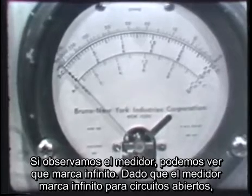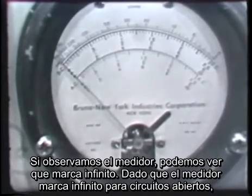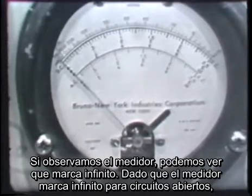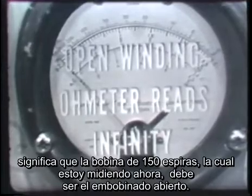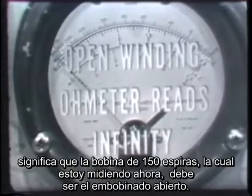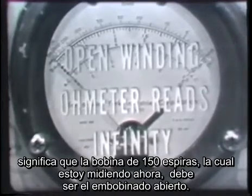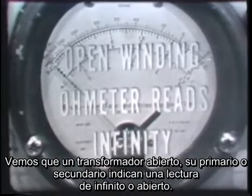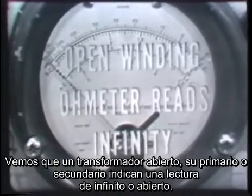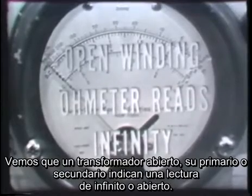If we take a look at the meter now, we'll see that it reads infinity. Well, since the PSM6 always reads infinity for an open, this then indicates that the 150 turn winding, the one I'm now measuring, must be the open winding. We see then that an open transformer winding, primary or secondary, is indicated by a reading of infinity on an ohm meter.